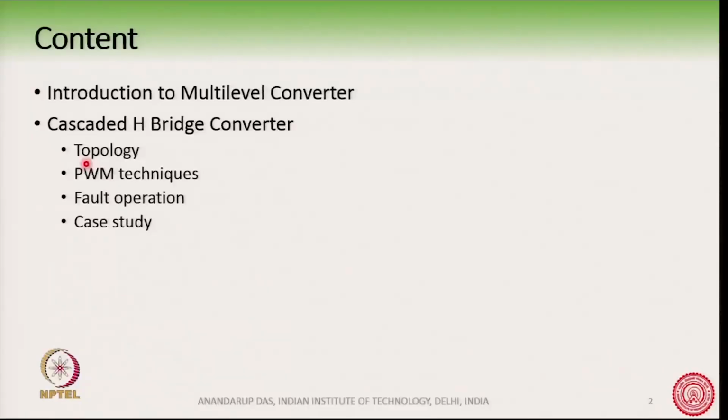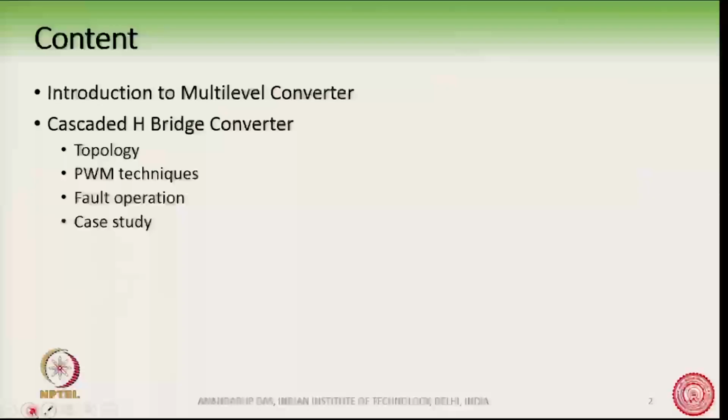In the last class we had introduced the topology of the cascaded H-bridge converter, and we saw that the H-bridges can be connected in series, and thereby we get a number of levels on the output voltage, which we saw that it will become closer and closer towards a sine wave, which we wish to generate from the converter.